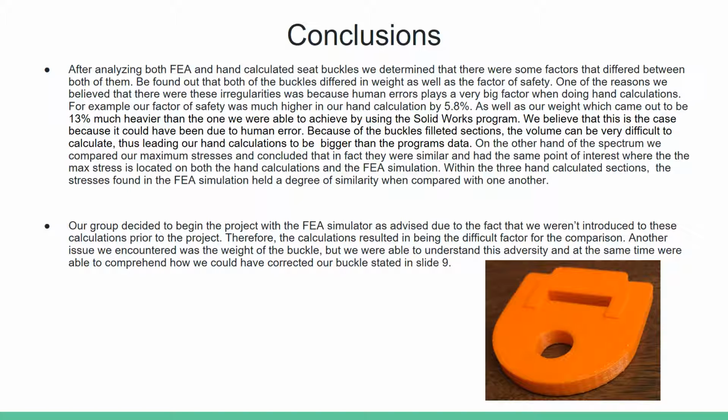On the other hand, we compared the maximum stresses and concluded that they were in fact similar and had the same point of interest, where the max stress is located in both the hand calculations and the FEA simulation. Within the 3 hand-calculated sections, the stresses found in the FEA simulations held a degree of similarity when compared with one another.